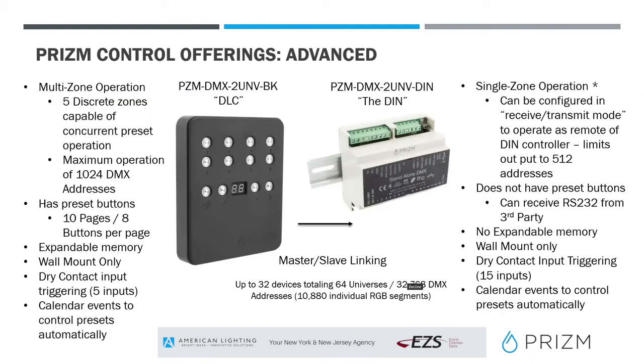Yeah, I mean, you could use a non-zone control DMX controller and have different shows going on in different locations, but it requires a lot more programming. But if you're looking at the picture of our controller here, there's a little screen and you've got a settings button and up and down arrows. So you get to the settings button and you get to one that says Z, and you'll have Z1, 2, 3, 4, 5, and then you can trigger shows based on whatever zone, or through the programming, you can have that done automatically.